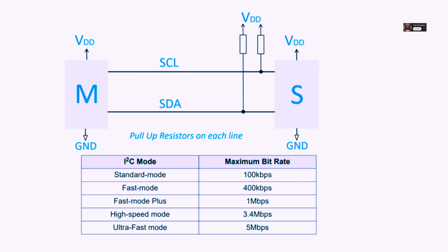That's a really important engineering trade-off. Yes, higher speeds mean faster data transfer, obviously, but they demand much stricter signal integrity. This means shorter cable runs become almost mandatory. The system gets more sensitive to electrical noise, impedance issues. Basically, everything needs to be cleaner electrically. Because the timing windows are tighter. Exactly. Those signal transitions from low to high, thanks to the pull-ups, need to happen much faster to be read reliably within the shorter clock periods.